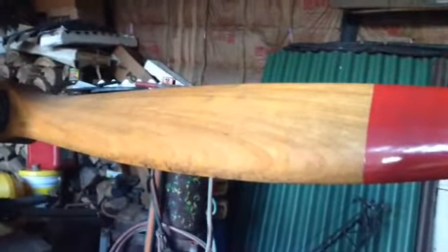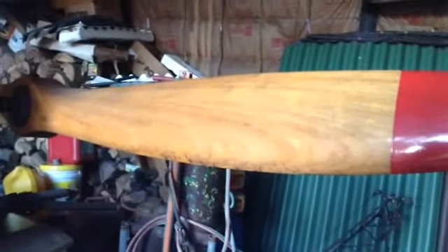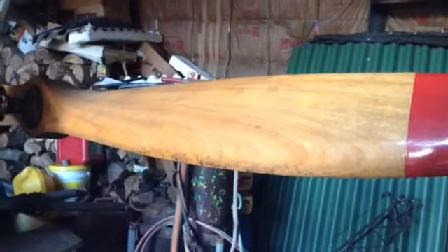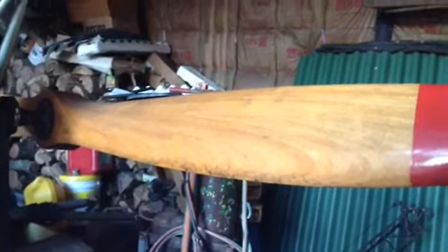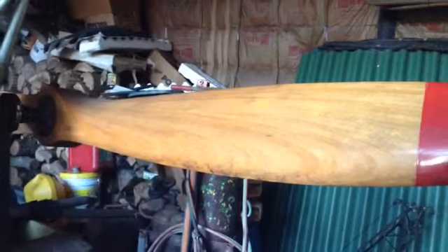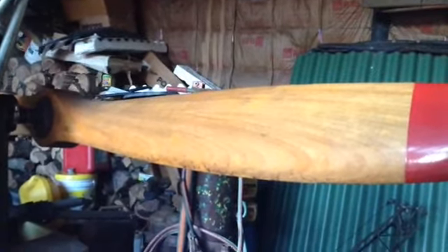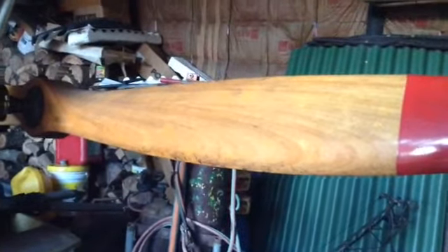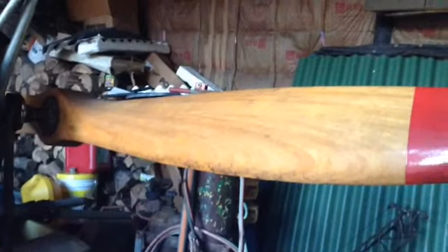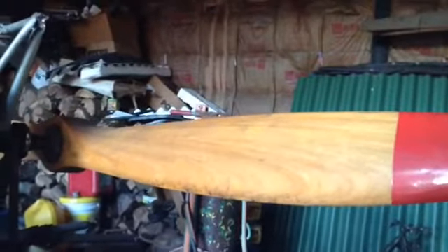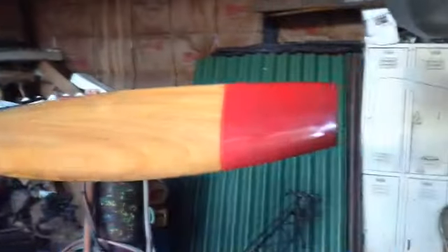If the propeller were shaped like a slice of pie, with its chord increasing from center to tip and its thickness remaining the same, its radius of gyration would be 1 over the square root of 2, or 70.7% of the radius, which would be 21 inches. But that's not the case. This propeller isn't shaped like a piece of pie. It's bigger toward the center than it is toward the tip. A piece of pie is small at the center and real wide at the tip, where all the crust is.